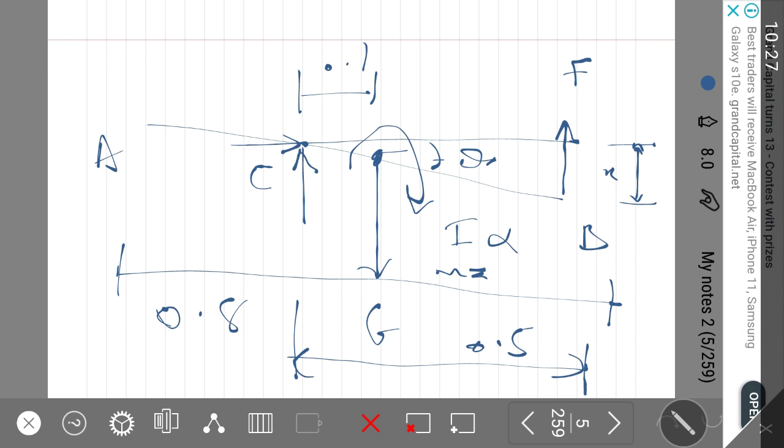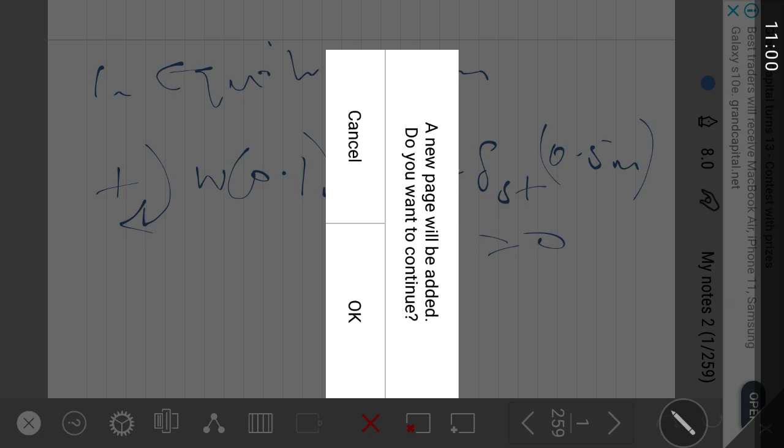In equilibrium there will be no x. So we have k times static deflection moving in this direction and the weight coming in this direction. The force is k times the static deflection, while the moment arm is the distance from here to here, that's 0.5. That's how we arrived at that.